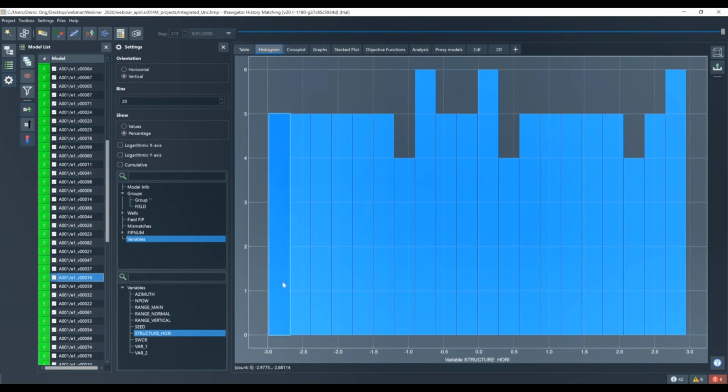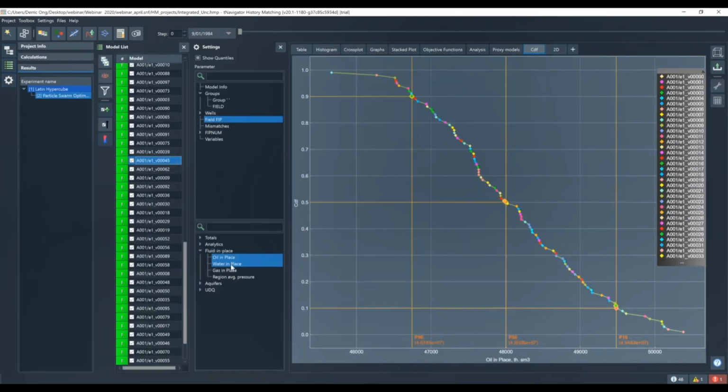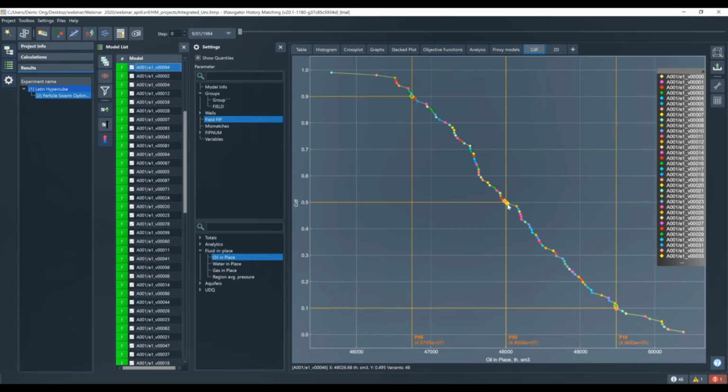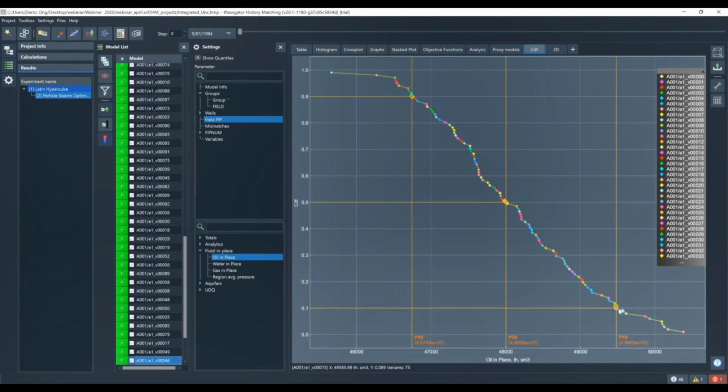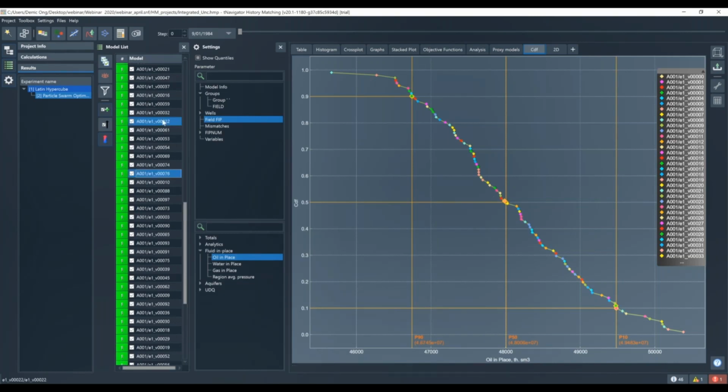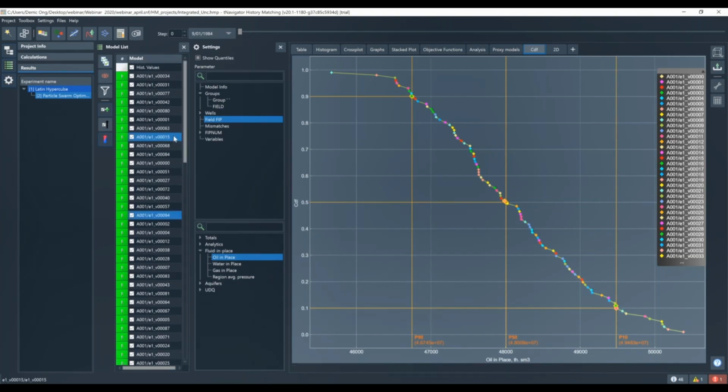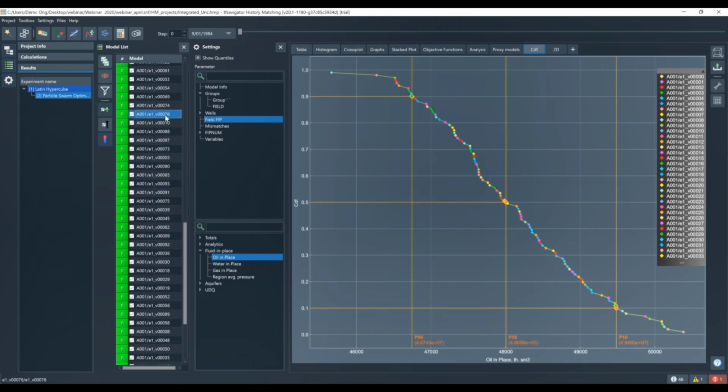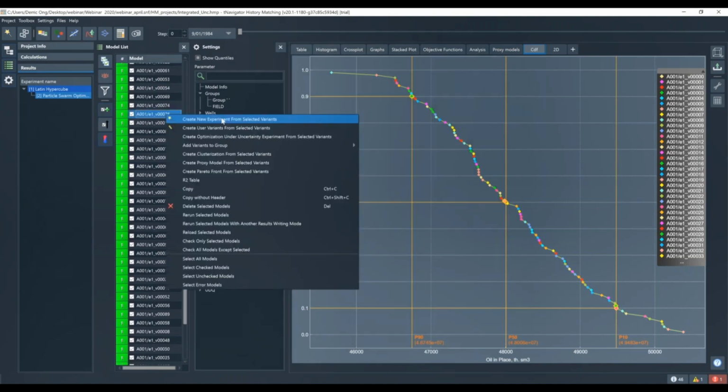There are several things that we can do here, for example, prediction mode or further optimizing my history matching. Here, I would like to show an example. I would like to optimize my history matching for my P10, P50, P90 models by simply clicking on the cases. As you can see in my model list, I now have 3 cases selected. I can right click and say I want to create a new experiment, which is my optimization. I only optimize based on these 3 cases.